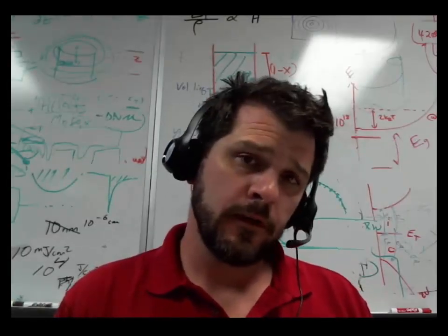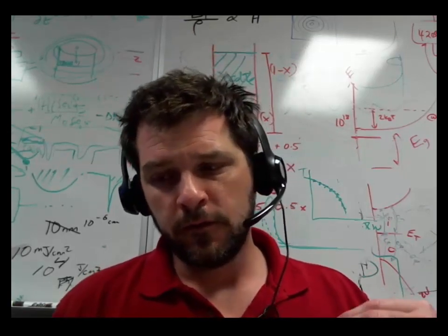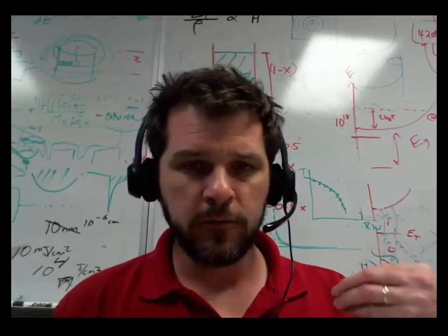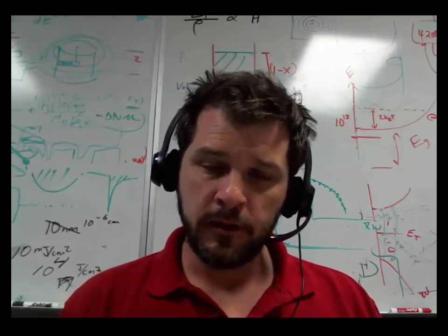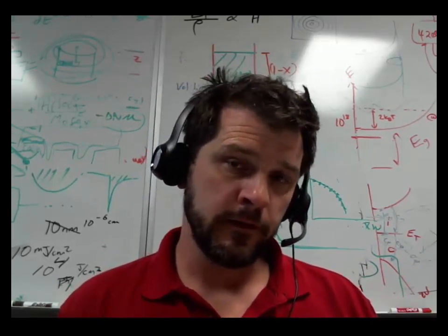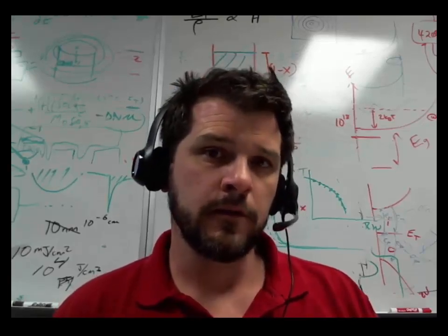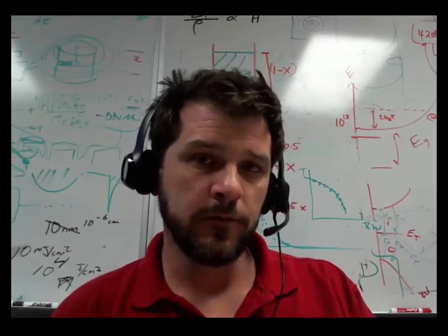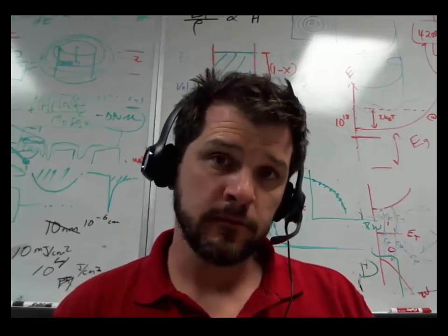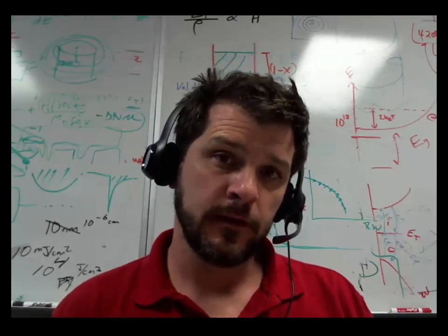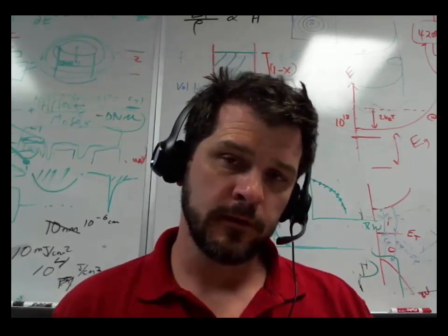Alright, so in these two videos here, we've gone through and seen the basic current voltage curves of the MOSFET. We've looked at phenomenology and looked at the equations that govern the source drain current as a function of source drain voltage. We've seen how the gate voltage affects things in terms of changing that channel charge and moving you above and below threshold to turn the device on or off.